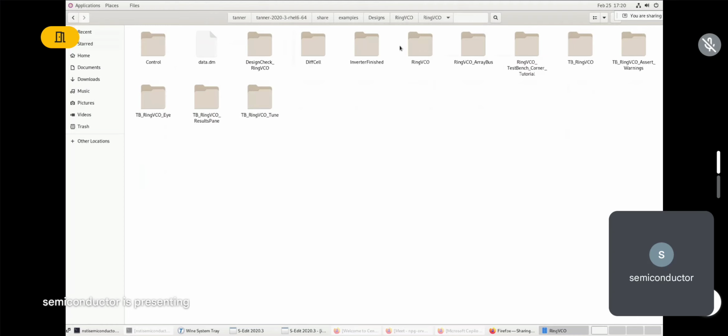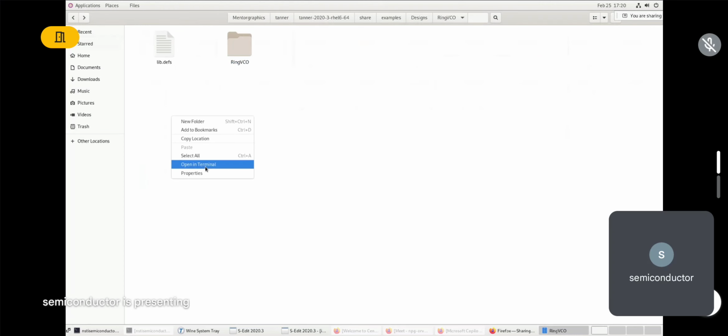Here there are lib.o files. You can directly open the terminal here, launch the tool at this location, and directly you will get the circuit. Observe how the circuit is. If you want to do it manually, just draw the circuit in your book and do it manually. Or else every setting will be ready, run the simulation and verify. So you have everything ready. Now why I am giving this inverter is so you will understand the tool flow. Once you are aware of the tool flow, you can directly run the example designs and then run your own designs.